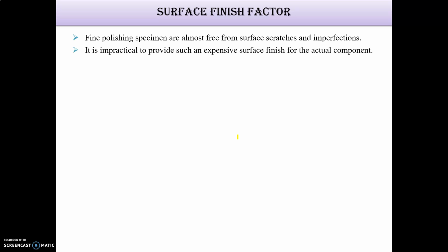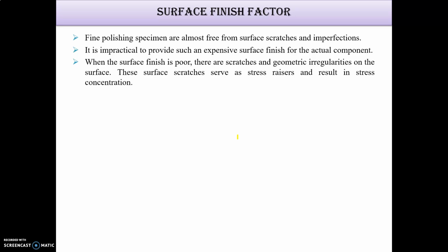Now let's see the surface finish factor, which is important. We know that fine polishing is not always possible, because if you give a fine polishing, definitely you are going to get a very good endurance limit, because it reduces all types of scratches, and scratches are nothing but irregularities, and they produce stress concentration points also, and affect the endurance limit. So it is impractical for all components, because it will definitely increase the cost.